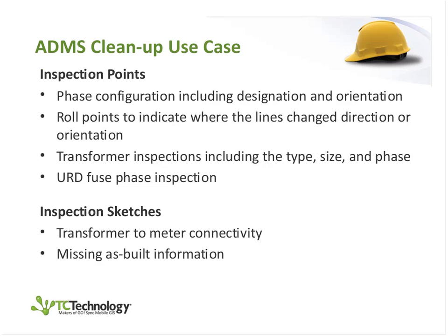Is it horizontal? Is it vertical? Is it a triangular construction? And then identify where there are changes in that phasing as wires roll from one construction to another, where you have taps going off to feed an underground development, things like that.